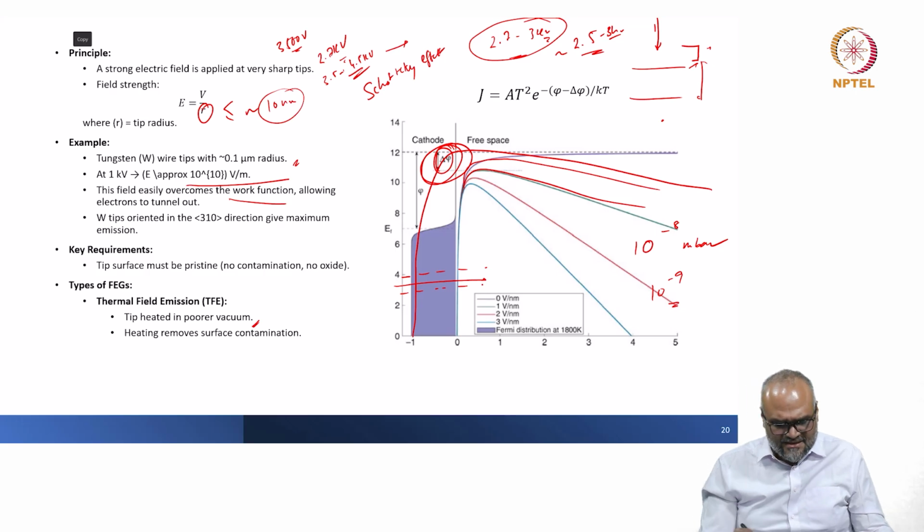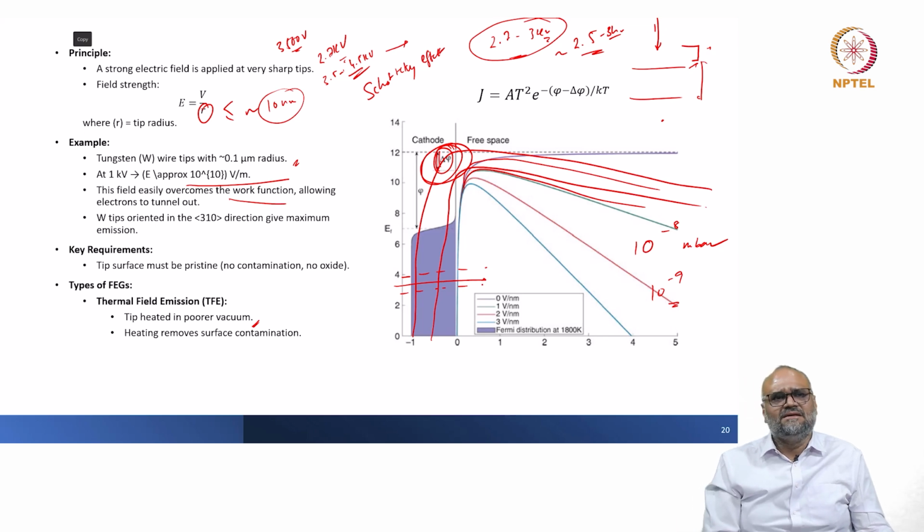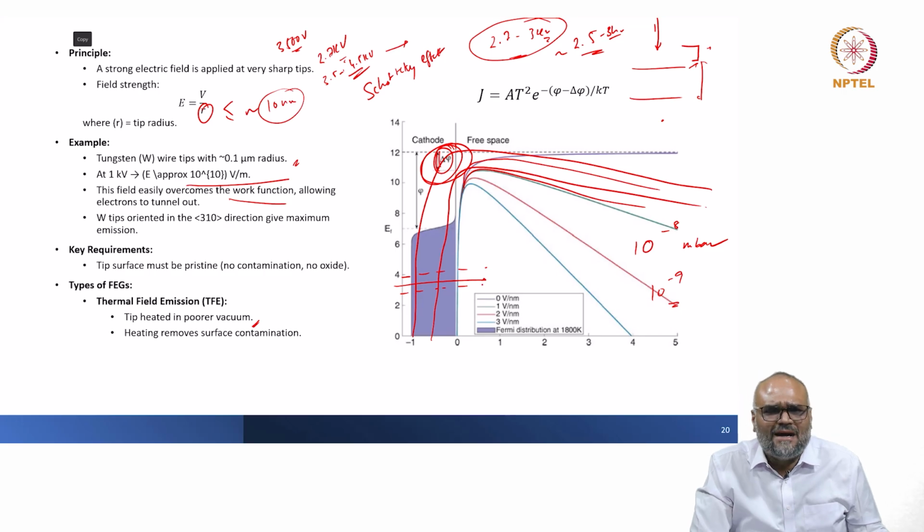So, in a thermal field emitter, with a gradual increase in the potential by doing a warm start, you can have sustained emission at a potential slightly lower than the work function barrier. And because you do this gradually and you maintain the emission current from the field emitter reasonably well, the stability of a thermal field emitter is not too bad in comparison with a thermionic gun.